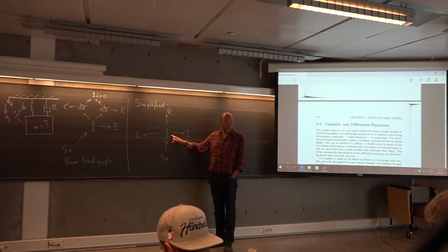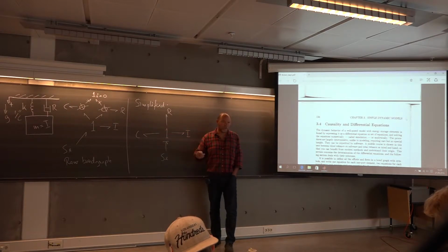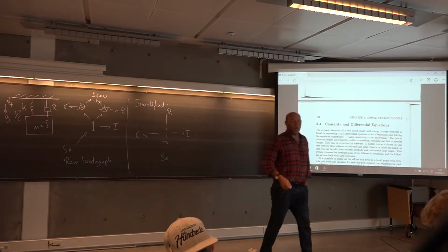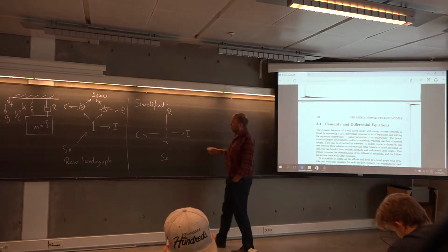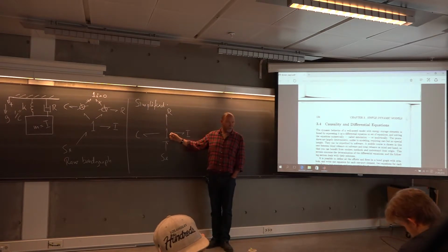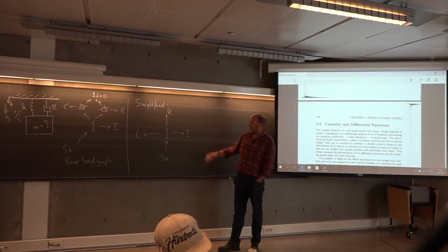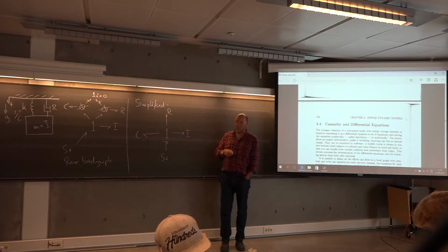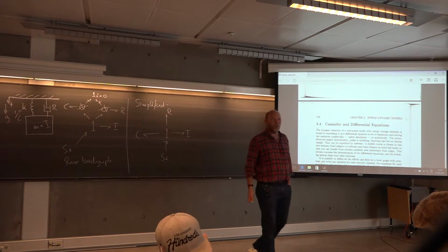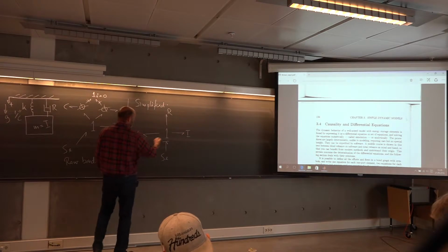What was the rule about the 1 junction? Well, a 1 junction, common flow, he should have all strokes towards him except 1. And the one where we are missing the stroke, that's where we find the flow that dictates what the flow should be on all these bonds, the common flow. So here we can't really tell, but I have a C and an I element, so there I choose the integral causal form, as long as I have somebody free.